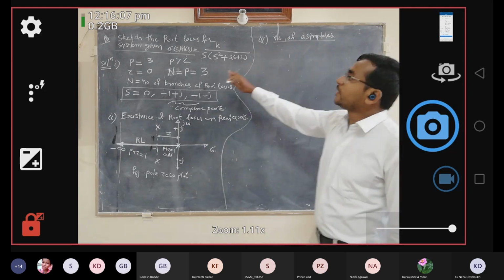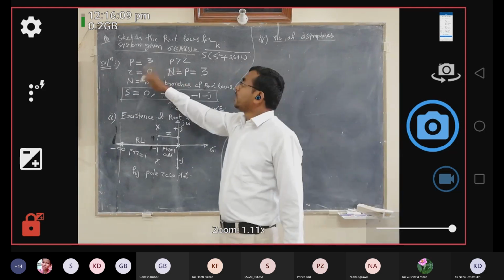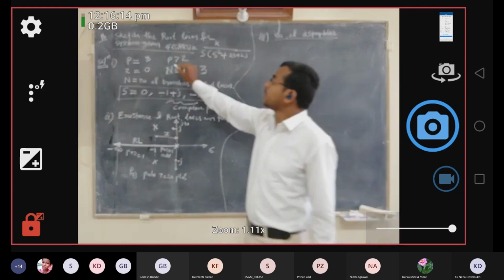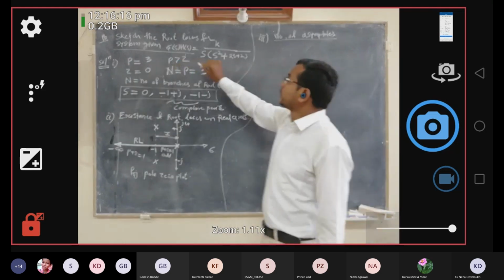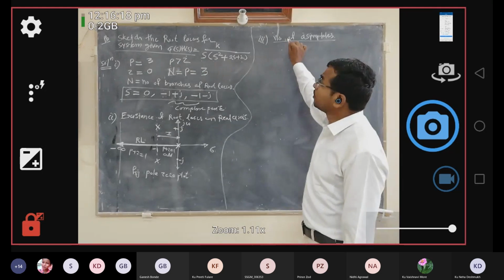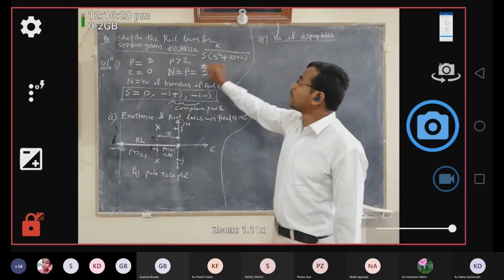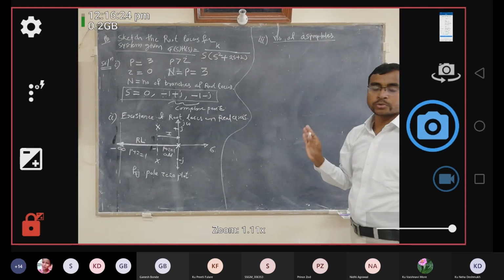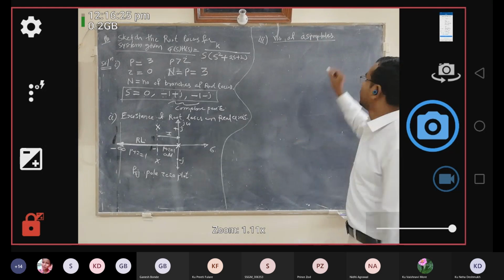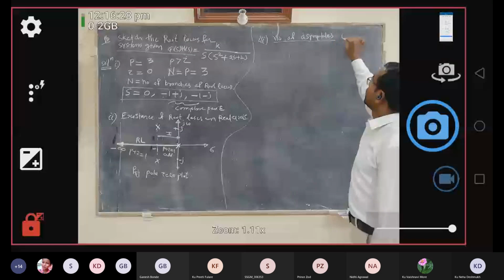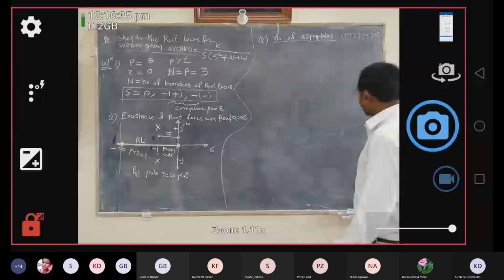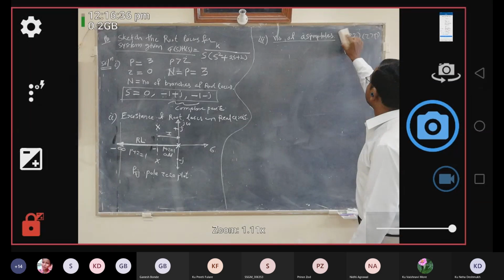When there is a disturbance between P and Z. जब तक आपके P और Z इक्वल नहीं रहेंगे, उस केस के लिए नंबर ऑफ asymptote प्रेजेंट रहेंगे. जिस केस में number of poles is equal to number of zeros, in that case there is no number of asymptotes. So please remember, number of asymptotes are present when P is greater than Z or Z is greater than P. ये दोनों केस के लिए नंबर ऑफ asymptote प्रेजेंट रहेंगे.